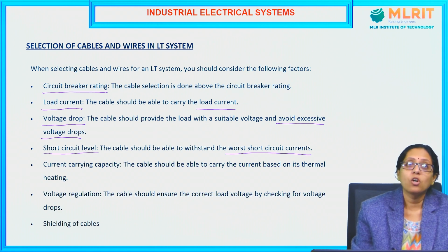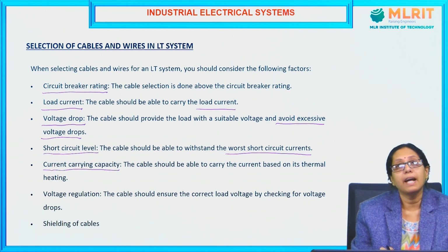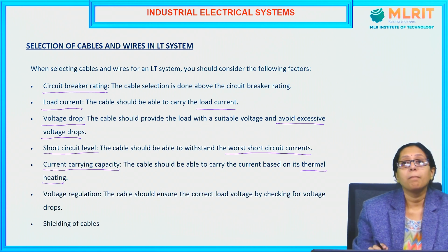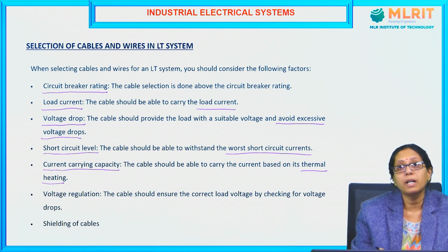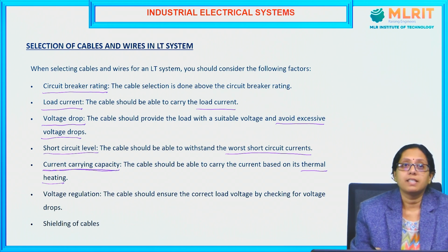So based on the short circuit current levels, the cable should be designed. Next one is current carrying capacity. The cable should be able to carry the current based on the thermal heating. Based on the thermal heating of that particular wire, the cable should be designed.